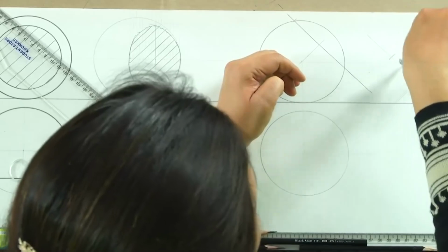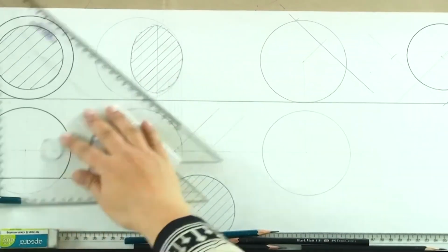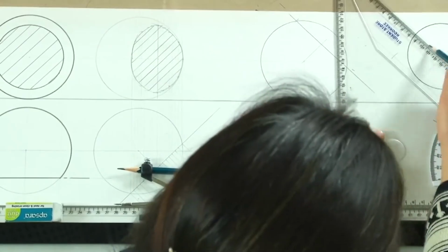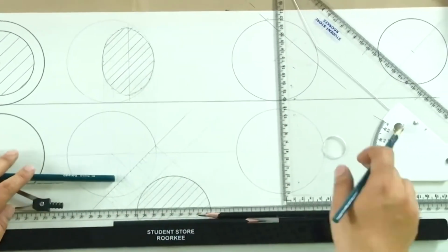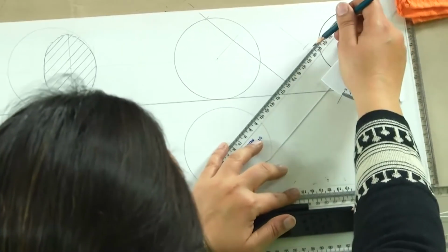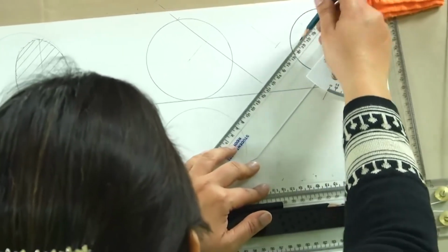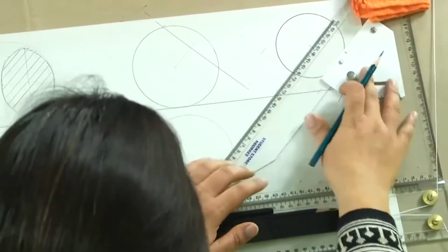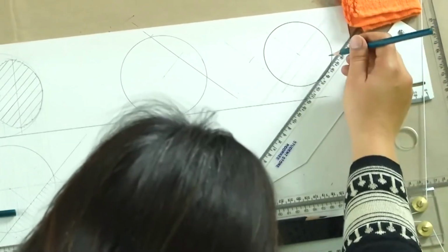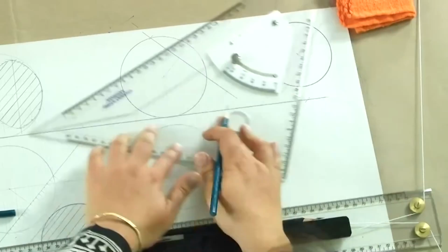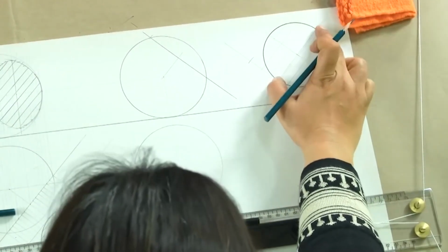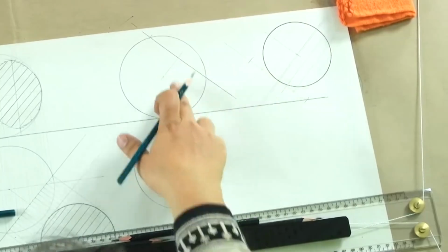Now what will we do? What's the next step? The next step is that we will draw lines on this diameter which are perpendicular to the diameter. So I am randomly drawing certain lines. It doesn't matter. Try to keep them equidistant as it becomes easier for us to locate points. And now the distance that you are getting here is the distance that we are going to get back here.